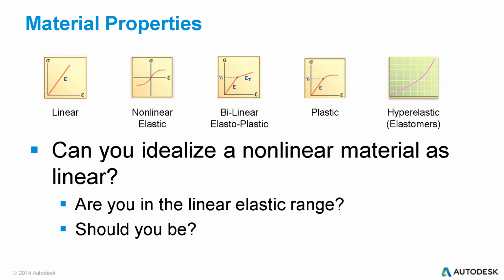They are different analysis engines, and through our own testing, we have found that the Inventor Pro, the Plazotech engine, and the Nastran engine, they give you the same results when you're running the same type of test. So if you run a linear in one and a linear in the other, you're getting the same end results. So you've got repeatability across the two packages, but Inventor Pro has those limitations to only work with linear and static loading conditions only. The other thing that comes into play is, if you're working with a nonlinear material, do you have to run a nonlinear analysis?